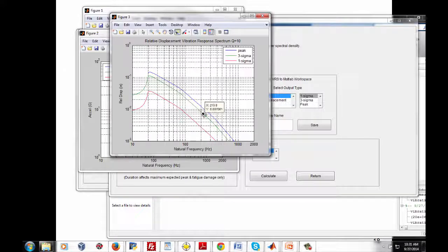And we're even in better shape yet if we have a higher natural frequency. So more longevity with a higher natural frequency. On the other hand, if we go downward in natural frequency, it looks like we cross the threshold at about 175 hertz. So at 175 hertz, the failure would occur close to 20 million stress reversal cycles.